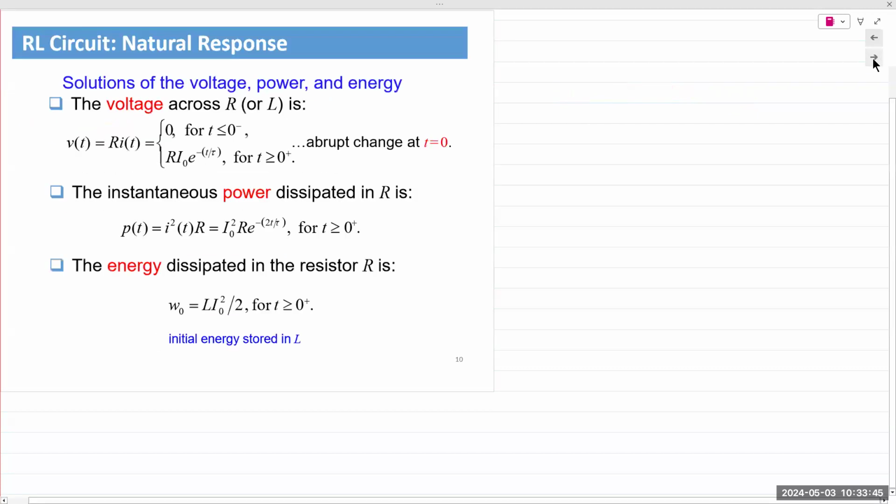If we have the expression for the voltage or the current, we can find the other quantity by applying Ohm's law. In this case, we obtain an expression for current, right? I of t. Simply apply Ohm's law and we can obtain V of t. So V of t is simply the product. V of t, again, we are talking about the inductor. So the voltage across the inductor will also drop as a function of time. As it loses the energy, the current starts decreasing. The voltage will also start changing. And that would depend on R times I.